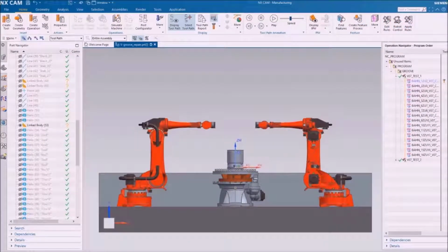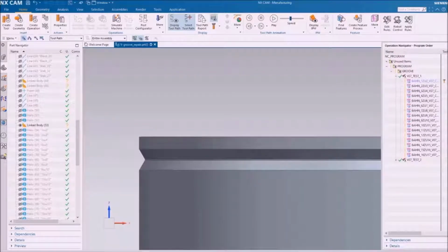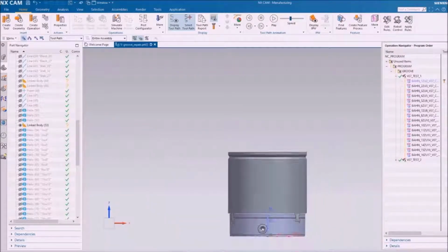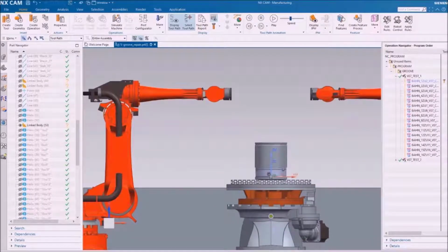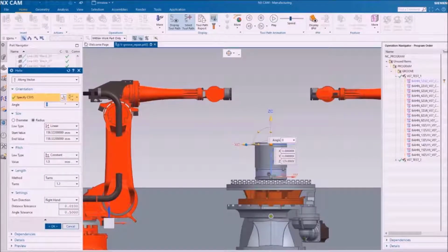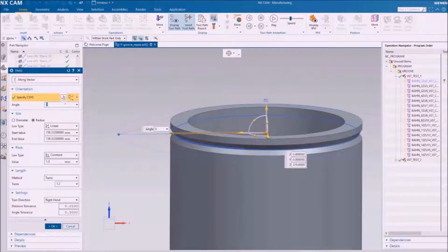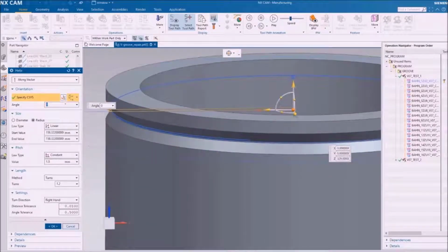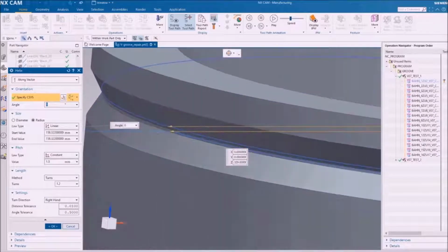In this use case, a repair task is to be accomplished using cold spray. There is a groove located on the cylinder surface. The side walls of the groove are inclined at a 70-degree angle relative to the surface normal of the cylinder. This V-groove shape requires a certain toolpath strategy, considering the local surface inclination to evenly fill the groove with repair material.